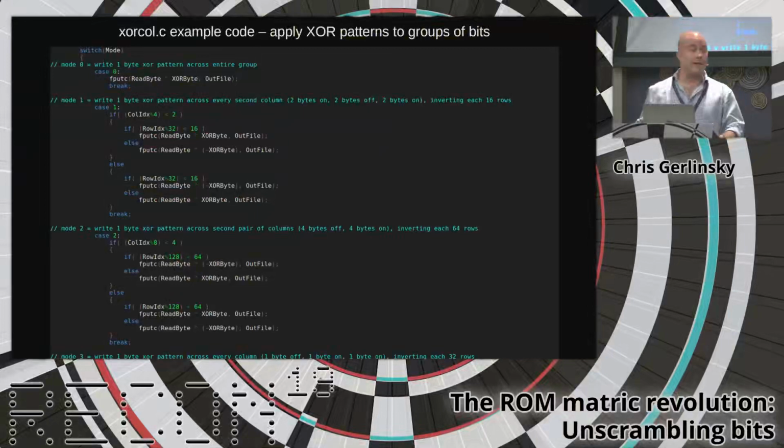Looking at the patterns, in this case I did have some plain text available from some of these chips. These ST19 smart cards are used in a variety of systems, and some of them have been exploited in other ways, for example glitching to extract code. For some versions of these chips, I had pieces of plain text code, and by comparing it to these visual patterns, I wrote a program that simply reverses the visual patterns that I see.